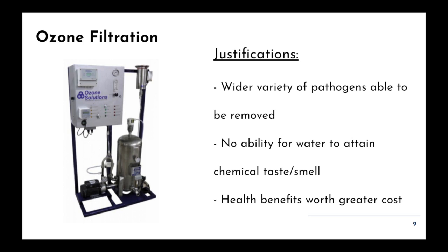When critically comparing to chlorination, ozone can treat a wider variety of waterborne pathogens and won't have a chance to give the water a chemical taste or smell. The initial cost of ozone will be $4,000. The energy required to disinfect will be 2 megajoules per ozone, and the minimum dosing of the device is 50 milligrams times minutes per liter.